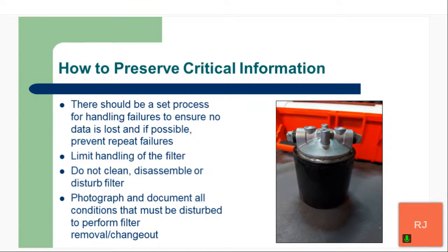We want to limit the handling of the filter. We don't want to be having a bunch of people touching it and looking at it with their hands. We want to not clean that filter. We don't want to disassemble it or disturb that. Ideally, we would like to capture that filter in the state that it failed and then get that to the laboratory to provide as much information as possible to them.